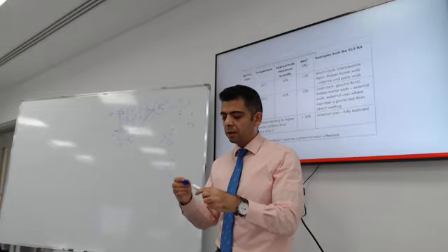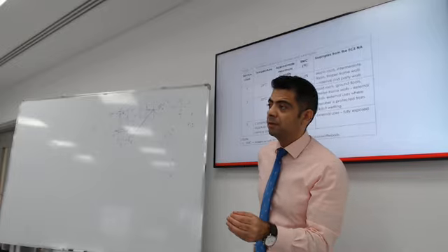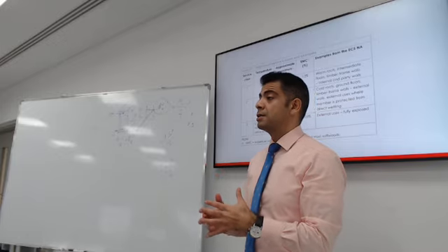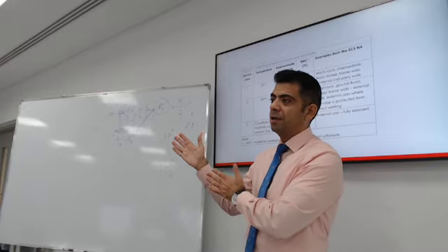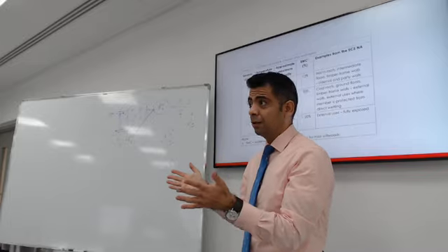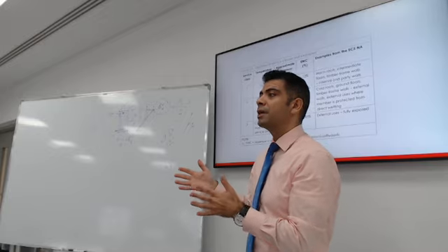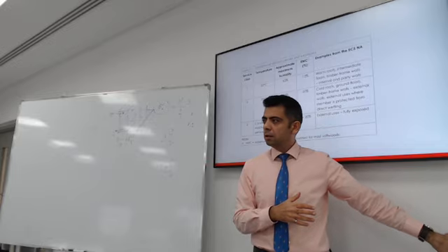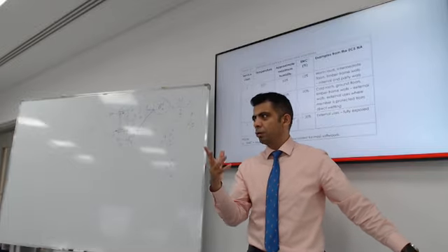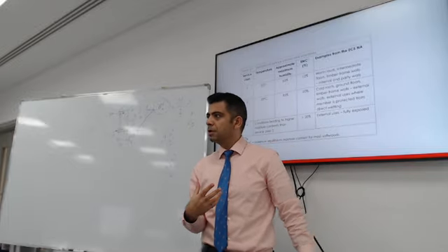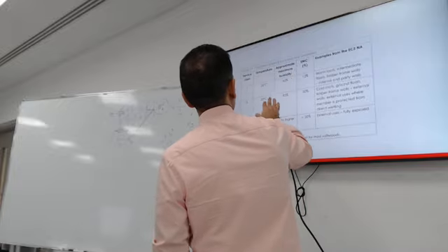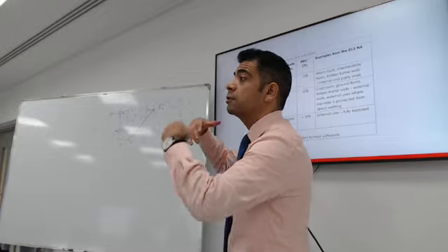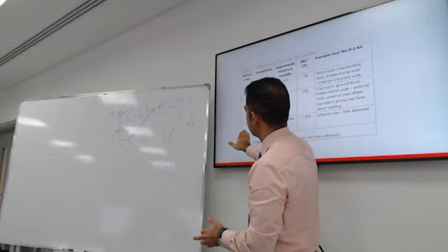It has to do with whether you are going to protect your structural member from the elements, or whether it is going to be exposed. So are you designing an outdoor shed that is going to be exposed to rain, wet, long time, snow, cold, or is this indoor? Do you notice how the indoor wall doesn't get exposed too much to rain or wind or sun, because it's indoor? If it's external use, fully exposed, that's called service class 3.